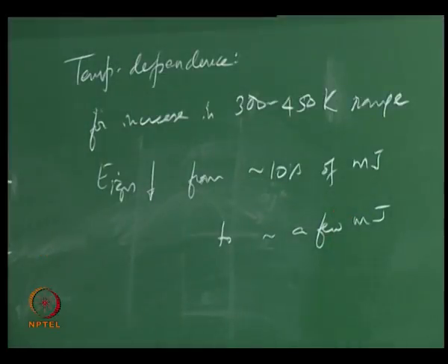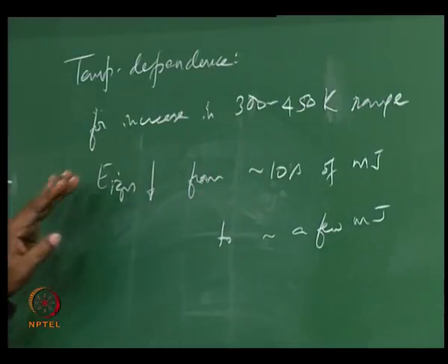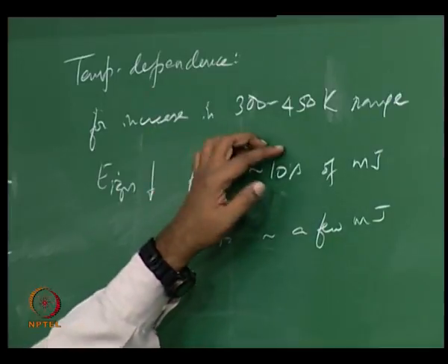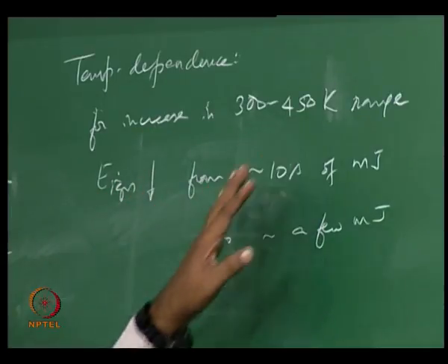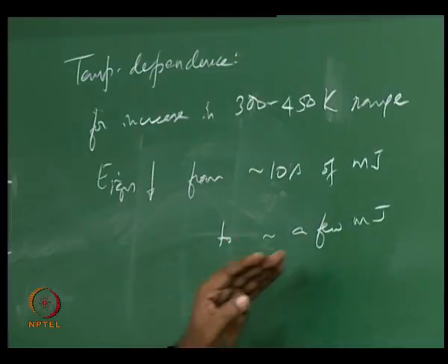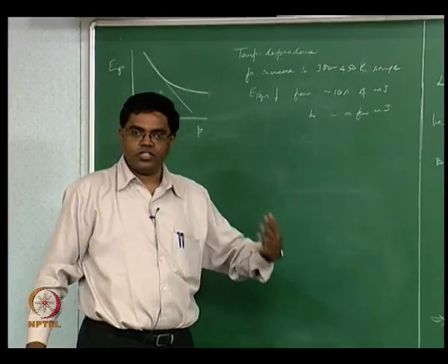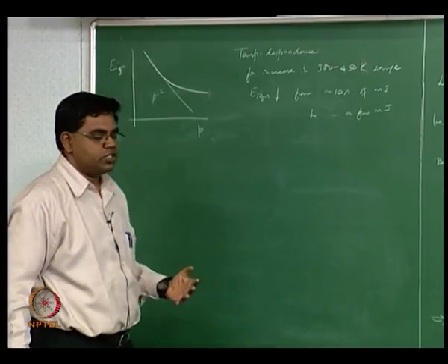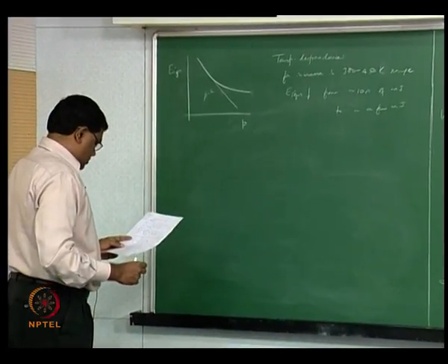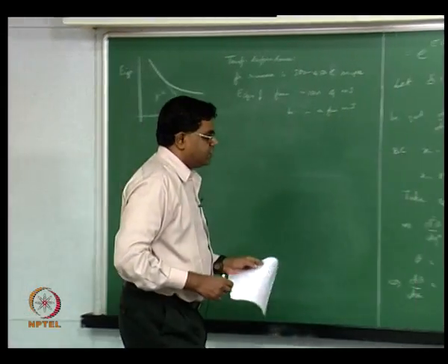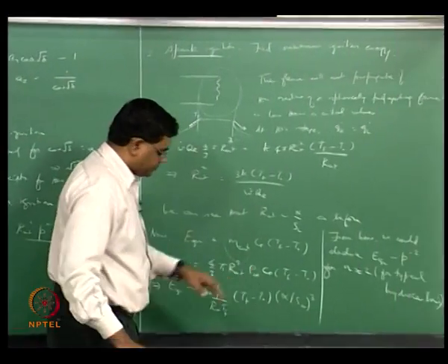That means we are looking at numbers like about 40 millijoules to 70 millijoules at 300K, whereas when you go to 450K, you need only about 4 or 5 millijoules, right? So as the initial temperature is increased, the minimum ignition energy required is correspondingly less. But you can actually work out how this exact dependence is yourself from here.